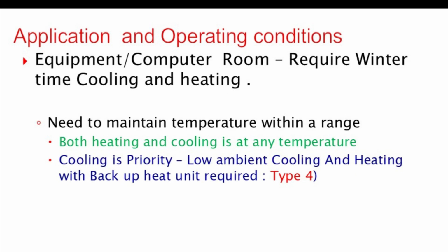Next, let's discuss an application where you need cooling during summer and heating during winter for equipment or computer rooms. In this scenario, you'll need a unit that provides both heating and cooling. The unit will require windscreens, low ambient cooling controls, and heating capabilities, which is a Type 4 system.